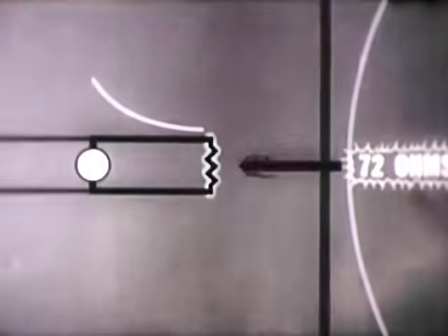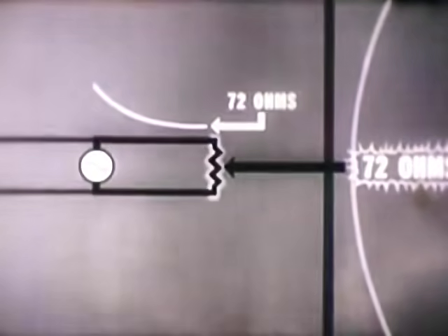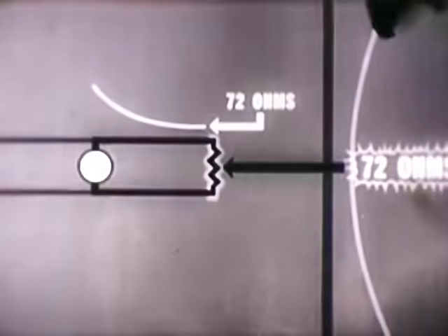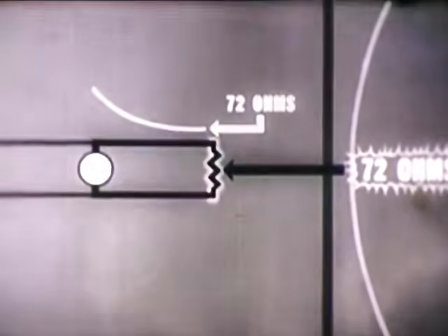Another method of impedance matching employs two lengths of metal tubing called a quarter-wave matching transformer, or Q-bars. These tubes are merely the twin wires of our old friend, the quarter-wavelength resonant line. In this sample closed line, the impedance curve is minimum at the closed end and maximum at the other. Now, supposing we put a resistor in the closed end of the line, say 72 ohms. Now we know that our impedance value at this point is 72 ohms. This changes our curve a bit, decreasing the impedance value at the generator end of the line because the standing wave is no longer at maximum amplitude.